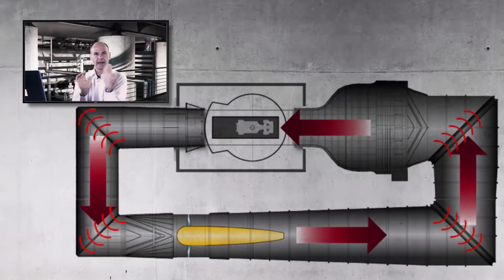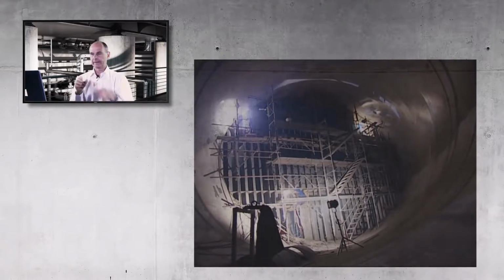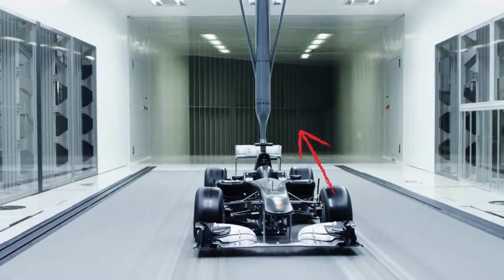We then send it through a couple of corners and towards the working section. Now in each corner we have turning vanes. You can think of them as a baffle, but what I would call them a turning vane. So in each corner there are a number of aerofoil shaped or curved devices that help the air to make the corner with the minimum aerodynamic loss of energy. And we have those in every corner. Without it, you just waste a great deal of energy. So this is something that early wind tunnels for over 100 years have used.